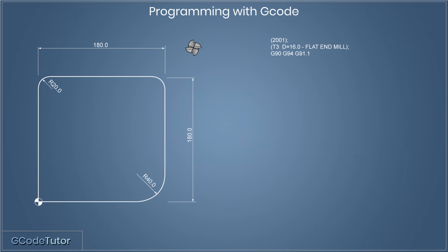The next G code here is G91.1. Now this tells the machine how to work out where the center points of the radius are. Are they in absolute or in incremental positioning? Well, the standard way for radiuses seems to be incremental. Both absolute and incremental are often used, but I see incremental a lot more than absolute. So this tells us that when we define the center point of a radius, we define it from the measurement of the last known cutter position and not the datum position.